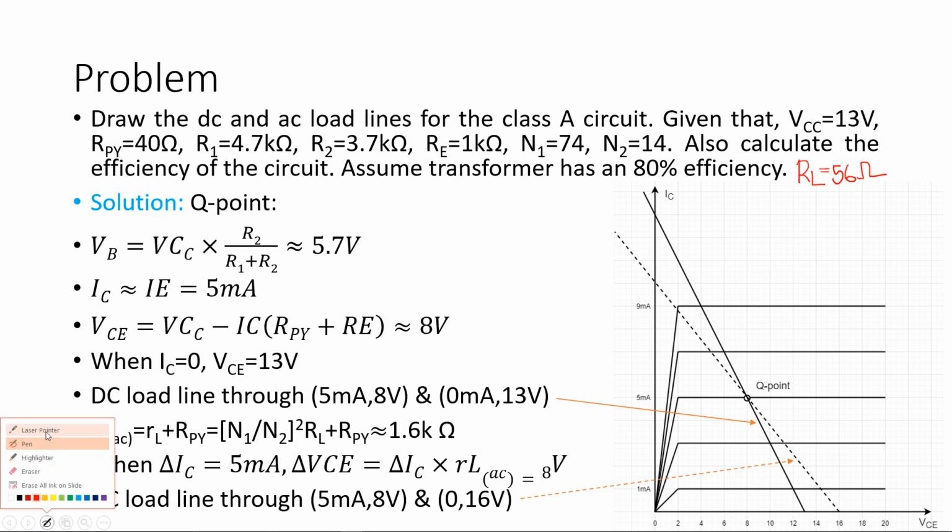See that it is in the ohm range, so the load resistance is very low. By using the transformer coupling, we have reflected the load by using the equations, and now you see the new resistance, that is the resistance seen by the amplifier, is very high, 1.6 kilo ohms.